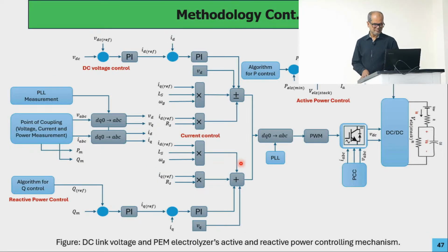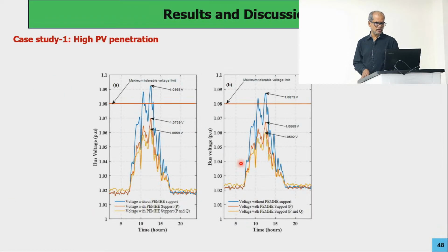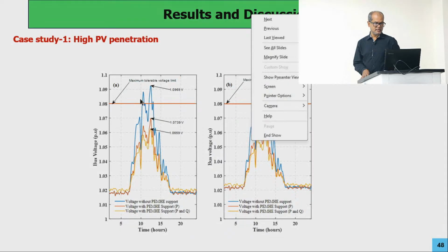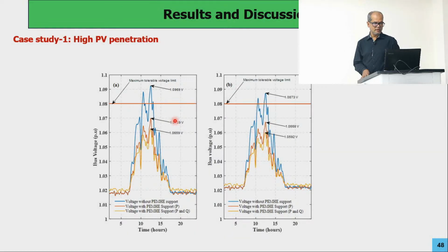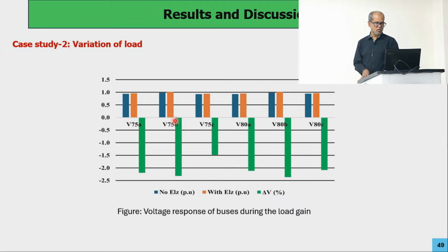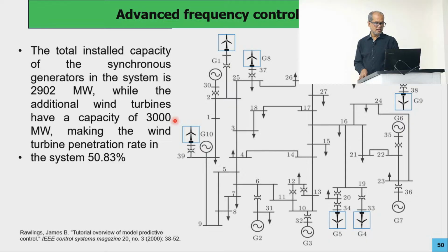So, how we design that sort of control. Also, here are the problems that we found in one of the Australian systems: during very sunny days, due to the power coming from the photovoltaic system, they got an over voltage problem. By using the electrolyzer, we could see how we could remove that problem, and what margin of the voltage they can actually change in the system.